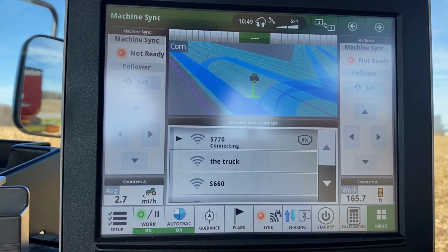Another place where controlled traffic mode off may work a little bit better is if you're dumping going both directions, say north and south. If you're shelling corn with a 12-row head, shelling lands, you wouldn't have to worry about recentering the AB line each time. When controlled traffic mode is off, it would continue to keep the same distance from the combine at all times.